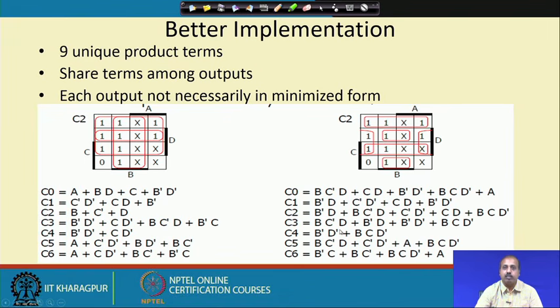So, this is actually a combinational logic minimization problem, and for multiple outputs, this is in fact a very difficult problem. There are many CAD tools available which do this type of optimization, where they try to share terms between the logic functions to get the minimum number of product terms for the whole function. Whatever minimization technique we have learnt using Karnaugh maps and all are for single output functions.